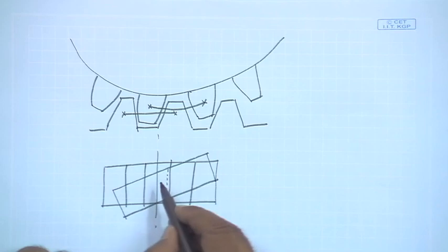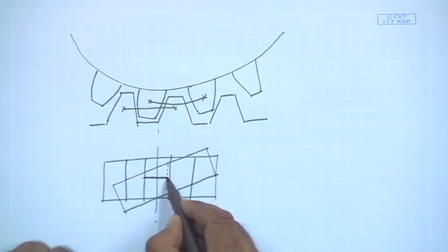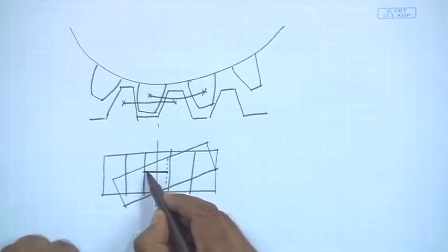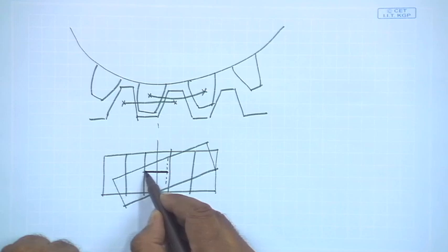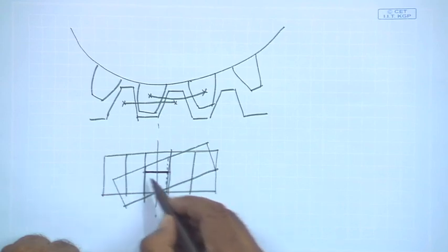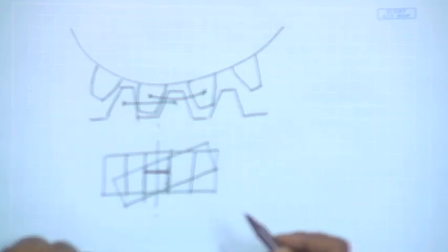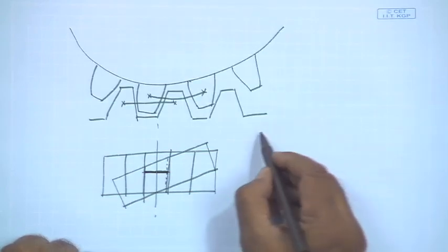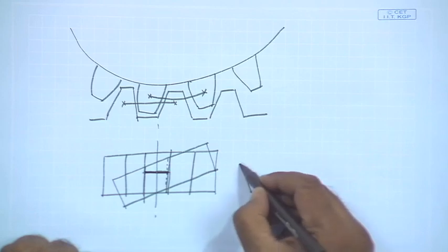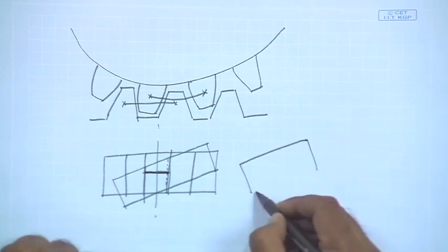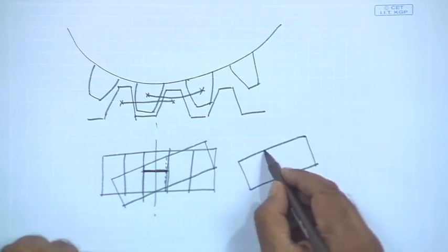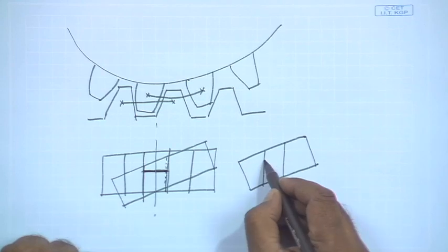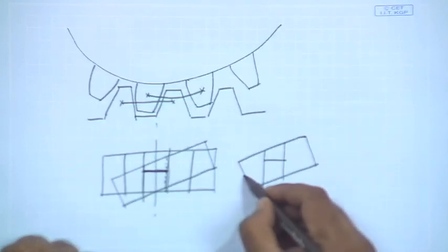So, basically this distance that we have shown as circular pitch, circumferentially this distance has to be equal to the distance between the threads, and that means the normal distance between the threads. If we look at the hob alone, it is this distance, not the axial distance.